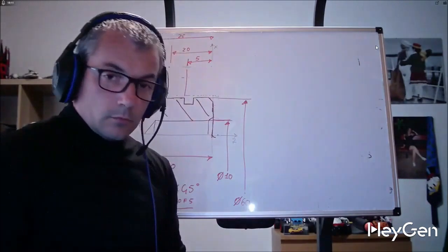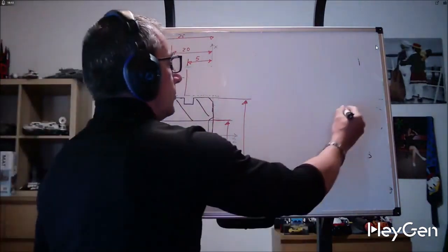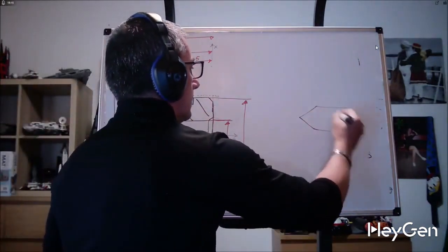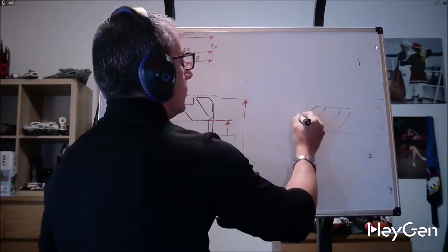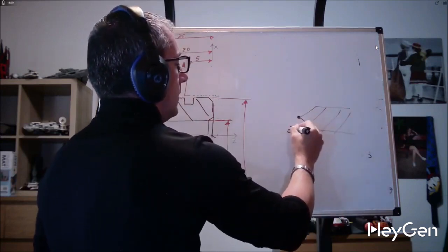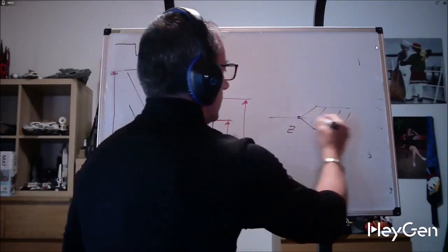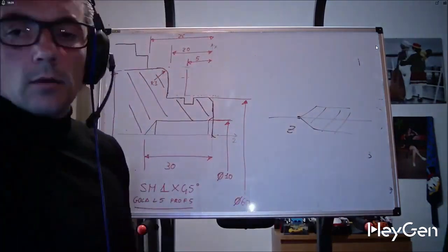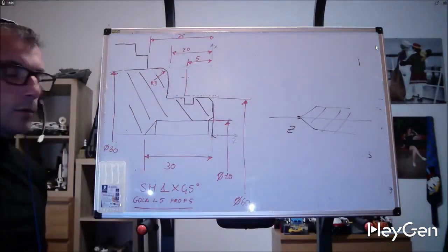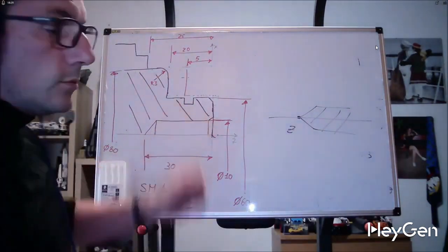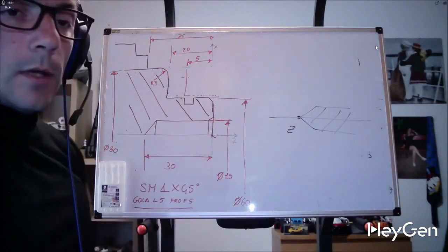So, to drill, just take a bit, zero it here in Z, and set it to 0 relative to X. When I want to drill with a bit, I always drill at X0, unless I use an insert bit. The insert bits are 180 degree bits.